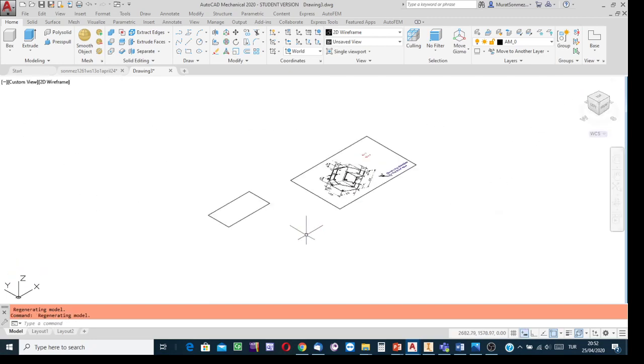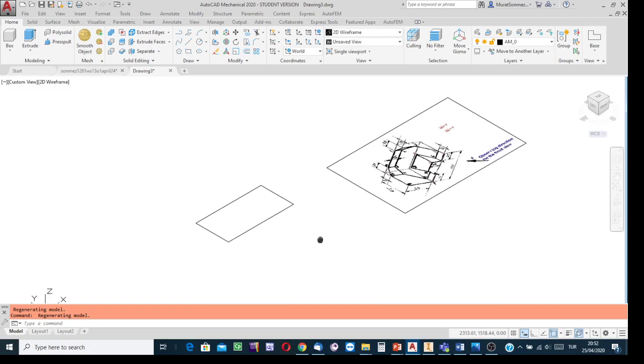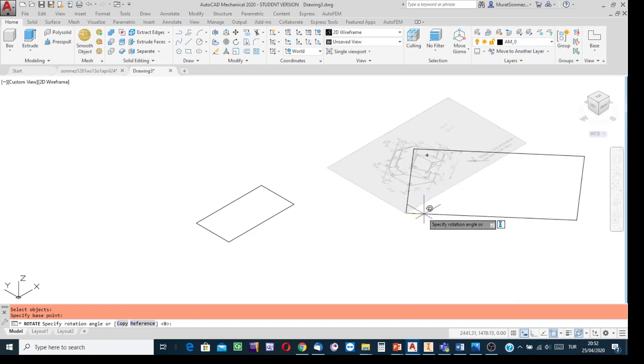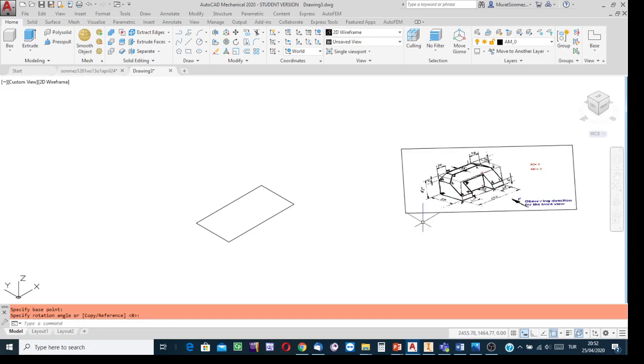But observing it in this direction, it is not so readable. Be aware, can rotate it. Apply rotation process, 2D rotation. Indicate this one. Press enter and then rotate it about such a base point. If you rotate it like this, then check whether it is more proper, more readable, more distinguishable.